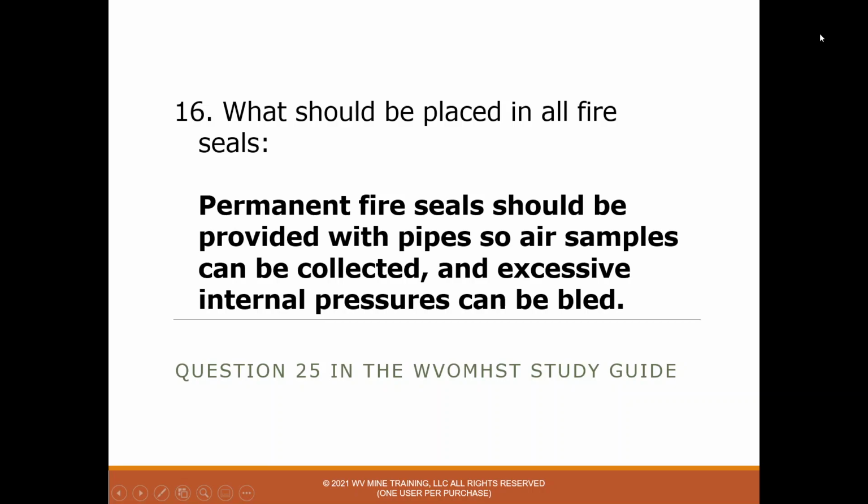So someone could access the front of that seal and tell what the gas condition is behind the seals. And also, excessive internal pressure can be bled. That is a water trap, so that when water builds up behind the seals, it will flow out through the water trap so water pressure doesn't cause the seals to be pushed out.